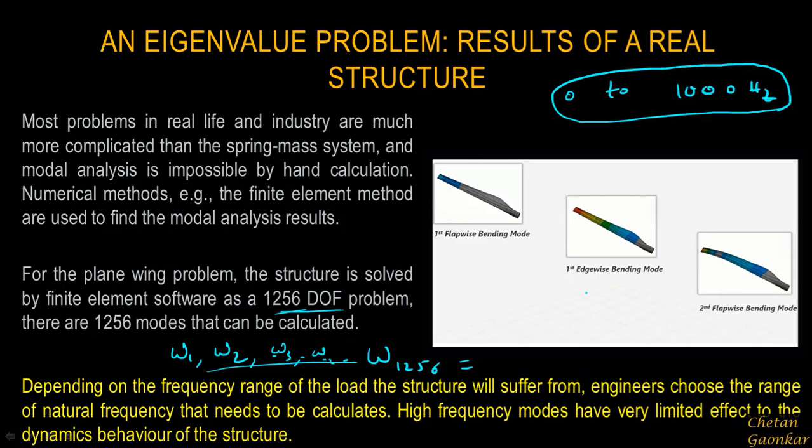So one has to carefully first understand to what range of frequencies this structure will be subjected to, and only within that range one has to extract the natural frequencies and study its mode shape. The higher order, high frequency modes have a very limited effect in the dynamic behavior of the structures, so we need not go for high frequency modes as such.